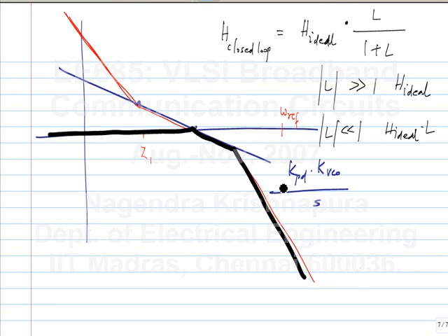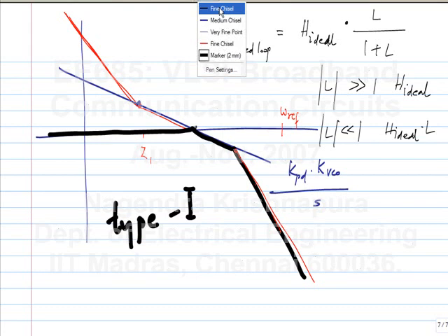The other first order PLL is not a very practical case because there is a severe trade-off between the lock range and the reference feed through, okay. And that had one integrator in the loop. Here we are talking about the phase domain model. So in that case, there is an integrator because of the VCO. The VCO integrates the control voltage to give you output phase. So if you have one integrator in the loop, it's known as a type 1 loop. I think you would know this from control systems.